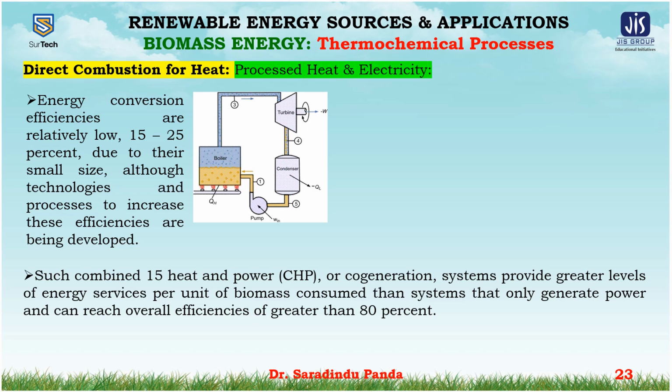The difference between cogeneration, direct fire gas turbine technology and co-firing is that cogeneration uses a boiler to produce heat and electricity, where the conversion efficiency is 85%. The electricity production from the steam driven turbine generators is 20 to 25% conversion efficiency. In the direct fire gas turbine technology, the fuel pre-treatment reduces the biomass to a particle size less than 2 mm and a moisture content of less than 25%. Fuel is burnt in the compressed air, then goes to the turbine, which produces the electricity. But in co-firing, the biomass is used as the secondary fuel, which could help to reduce sulfur dioxide and nitrogen oxide emissions and decreases the net carbon dioxide emissions from the power plant.